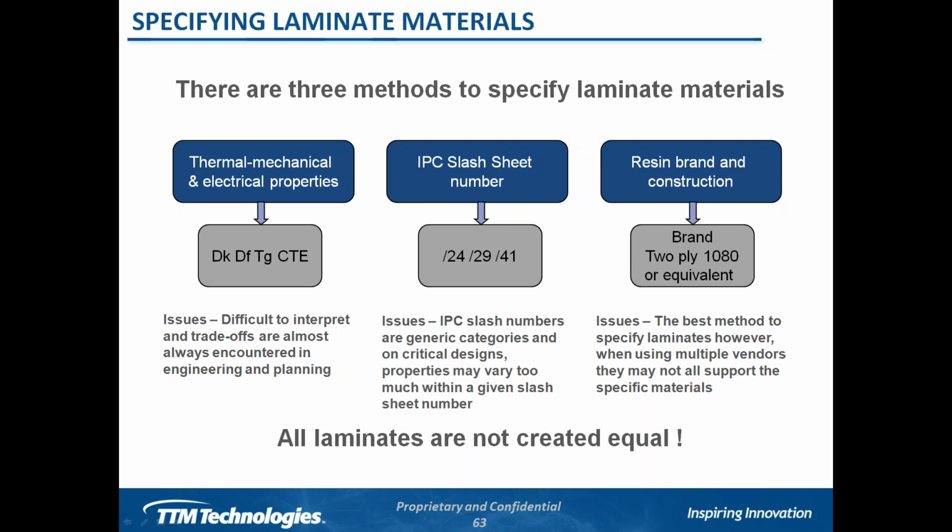But if you're looking at option number 3, always try to work with a fabricator first, because that's how you're going to define the stack up that at least you know is going to work for at least one fabricator. If you try to do this on your own, working with unpressed thickness tables or materials that may not be available at a fabricator, you will run into trouble at some later point.